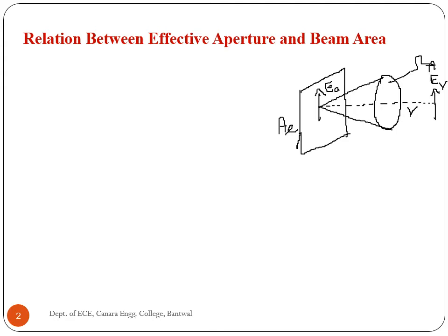Suppose that the receiving antenna is a rectangular electromagnetic horn immersed in the field of a uniform plane wave E. If the horn extracts all the power from the wave over its entire physical aperture, then the total power P absorbed from the wave is given by P is equal to E square divided by intrinsic impedance into physical aperture, or I can denote this as S, the Poynting vector, E square divided by Z naught into A, physical aperture.